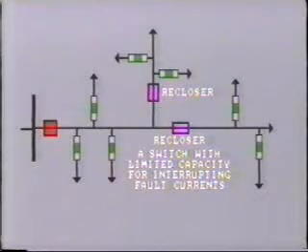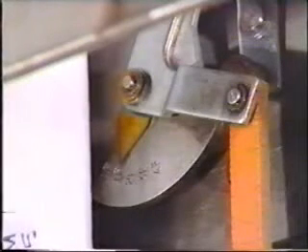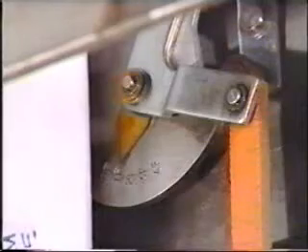This is acceptable because very high levels of fault current occur closer to the feeder breaker, which has greater interrupting capacity. However, further down the line, fault currents are less, and the local recloser will clear that section of line and then attempt to reclose. The operation of the recloser is mechanical, and usually up to 4 attempts are provided with time delay settings between each attempt.